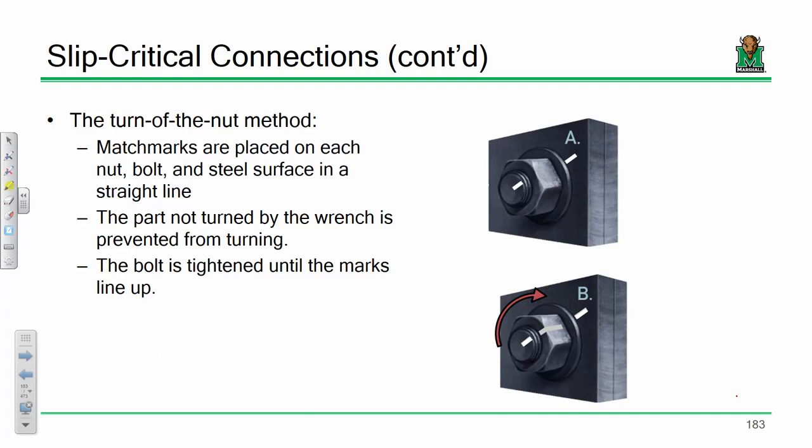And then you get a big iron bar or big iron spud wrench, and you turn that, you put effort into it and turn it around so that the bolt has engaged that third of a turn, and you'll see that those marks line up. And so that's a code allowed, specified way of achieving that predictable amount of pre-tension.